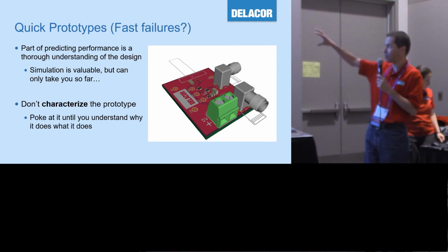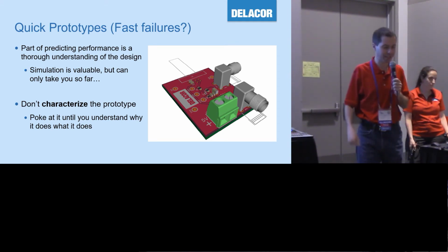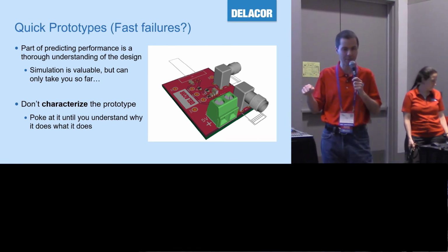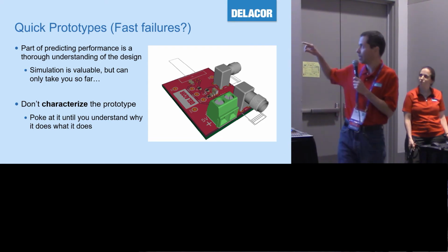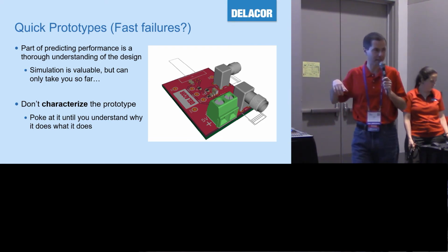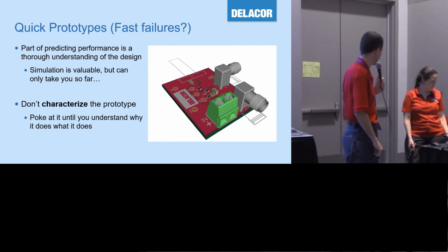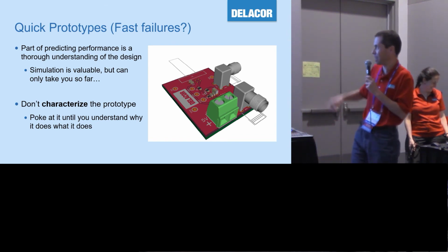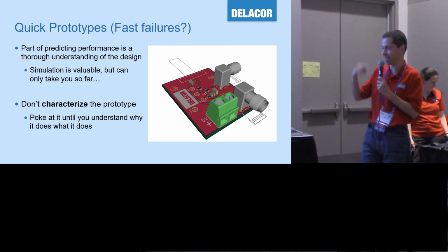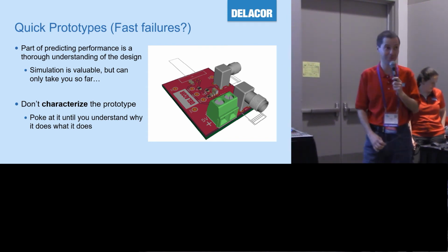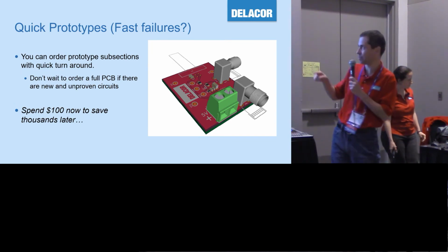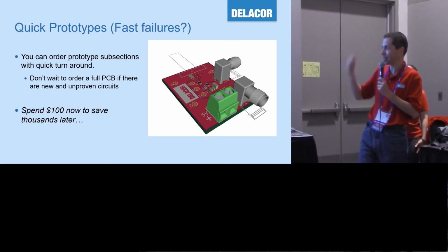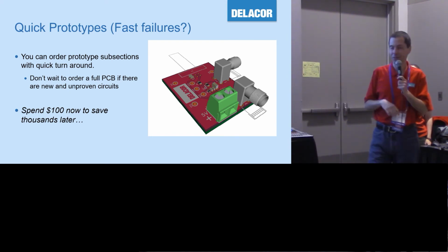And we want to be careful. This doesn't mean you make a board and you characterize it and you measure it, and hey, I measured a volt here, that means every one of these boards I make is going to be a volt. It's really, I built this thing, and again, I said I wasn't going to talk about expectations anymore, but I built this thing and it works the way I expected it to. So that means I can put that circuit on my board because I understand it. Or hey, this doesn't quite do what I thought it would do. Let me poke at it and measure everything and make whatever changes until I understand it really well, and then I can go put it on the main board.